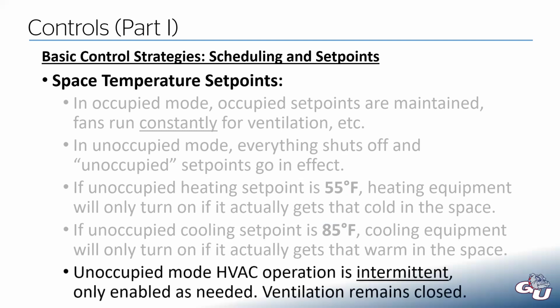And another way this saves a bunch of energy is the unoccupied mode operation is intermittent. It's only enabled as needed. So this is more of a cycling of equipment, as opposed to when we're in occupied mode, we have to run the fans constantly for ventilation. In this case, ventilation is closed if we're in unoccupied mode.